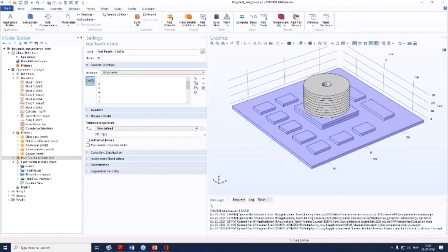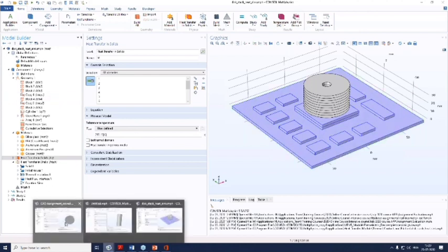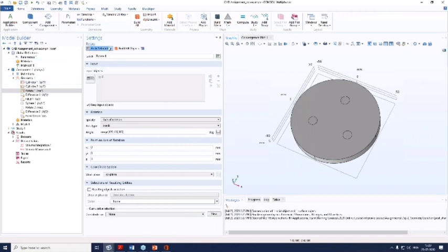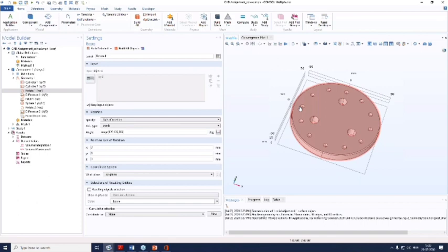Again, in this assignment, the smaller circle was not completely removed. How can we do that? It was not supposed to be removed completely, and these are not circles, these are spheres, as you can see. You need to ensure the depth of that sphere which is getting inserted inside that circular disc. Here in this case, as you can see, the depth of that sphere inside the circular disc is equal to the radius, and accordingly you can first of all draw the sphere and then remove it.